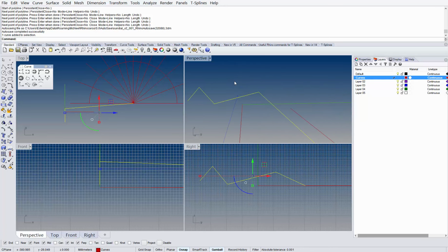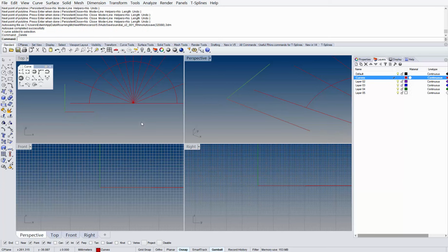You see how it goes off? So we shouldn't worry too much about that, because I haven't shown you anything that would make your drawing not flat. But sometimes that happens when you're snapping to 3D objects on top view. You'll make a drawing that looks like it's flat from top view, but it actually won't be.